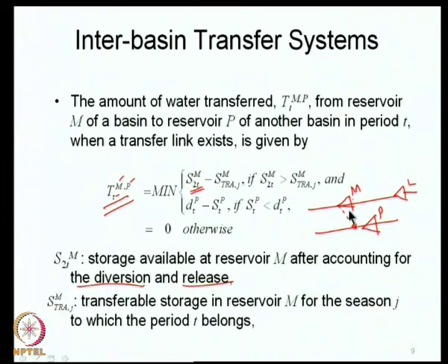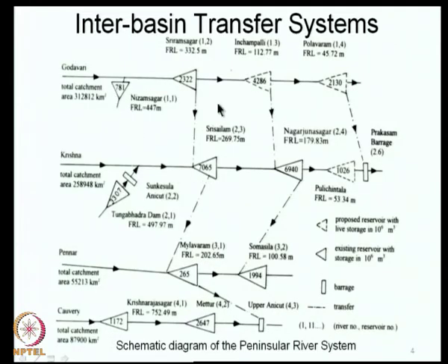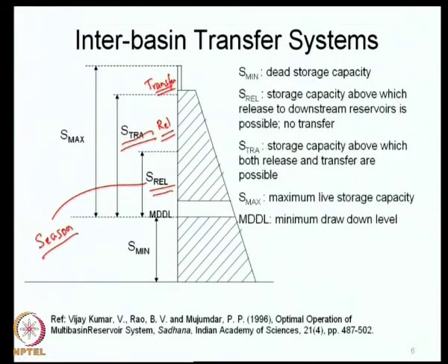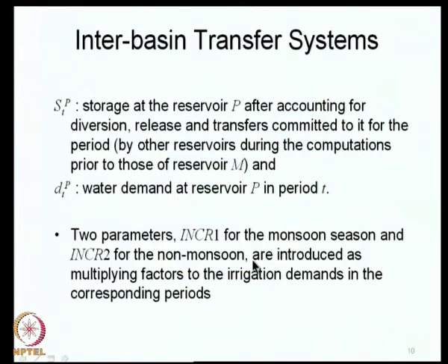Then at every reservoir you will have storage continuity, you will have its own constraints and so on. So, all of these are typical multi-reservoir system simulation which I have discussed earlier. So, at every reservoir you meet the storage continuity equations and then you put on top of all of them the release policy as well as the transfer policy, and then you simulate the system. So, this is the transfer policy and then we will do, as I said,